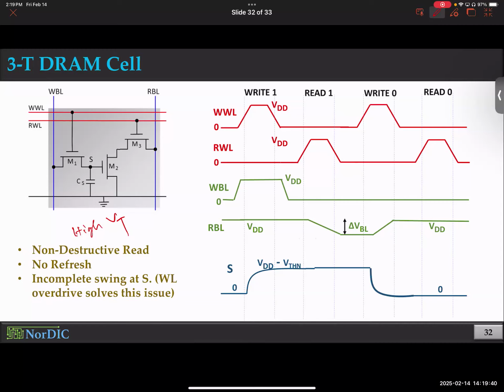Yes, that's true, that's one of the things. Of course, you can make things slower by making the clock slower, so everything works slowly. That's why things become slow as well. But there is one other thing that is taking place. Well, not just one other thing, many other things. It's a collection of techniques that are imposed when you select power saving mode. But one major thing is body biasing, as we call it.